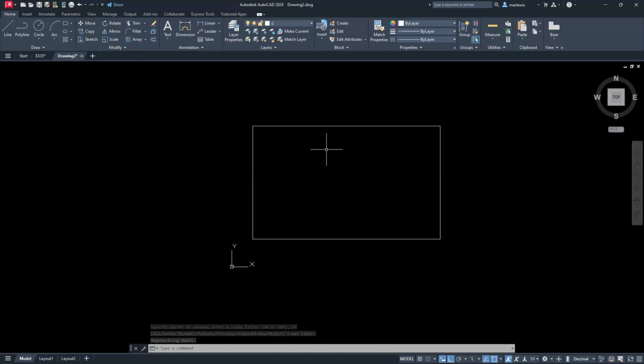Alright, so what I want to do on this is offset these lines. Now remember that this is a polyline, since I've created it with the rectangle command. So I have two choices: I either have to explode this or I can use the construction line method. I'm going to use the construction line method. It makes things super easy, and that way I like to keep things, if I can, all as one polyline. It really is not that relevant in this drawing, but if you're creating some kind of super big drawing, every line does count. You can tremendously save space with your file sizes by keeping things as polylines and blocks and things of that nature.